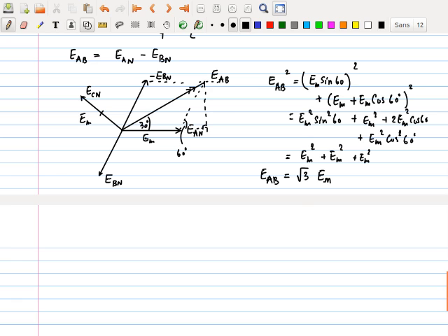So you realize if I take the amplitude of a single phase, and I want to find this line to line voltage, I have to multiply it by root 3. Now basically if you take this household system, each of the single phases would be 240 volts, right? 240 volts.